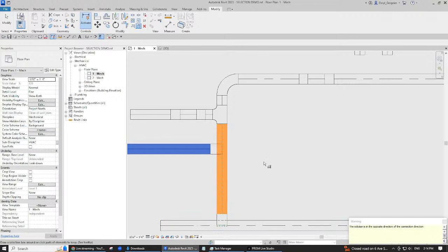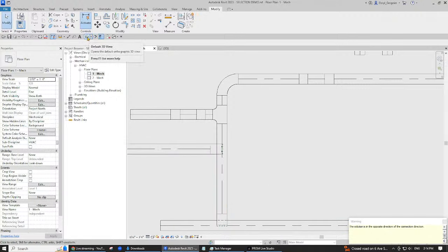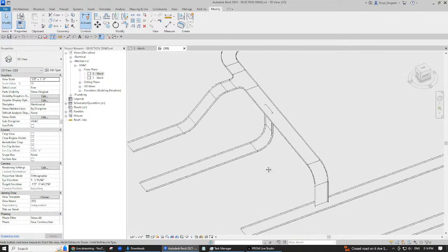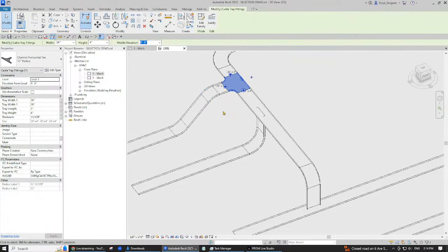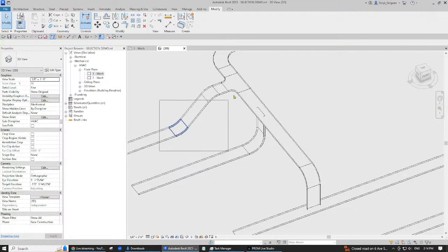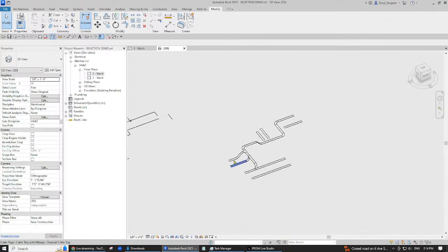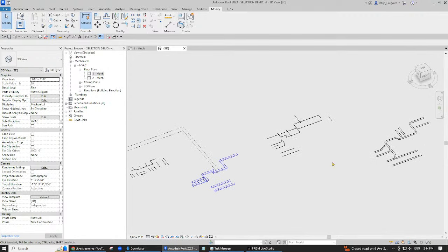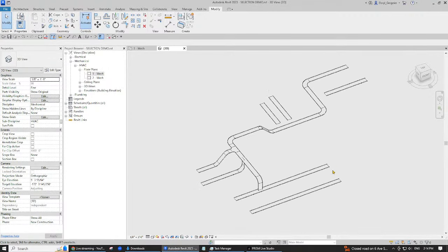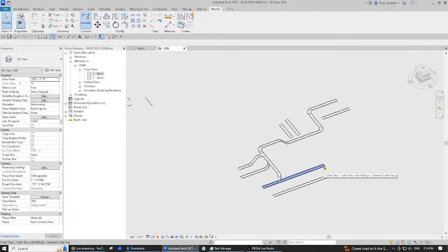It didn't try, it did it, but it had enough room, interestingly enough. See that? If it has enough room, it'll curve it right up. If it doesn't have enough room, it puts two 45s in there and then puts in a T instead. So this is when it doesn't have enough room to get the 90 in here. Needs enough room to get that in and get that next piece up there. So trimming and extending, pretty much the same, works with duct, pipe, conduit, and cable tray, and walls and beams as well. So I just wanted to cover that.